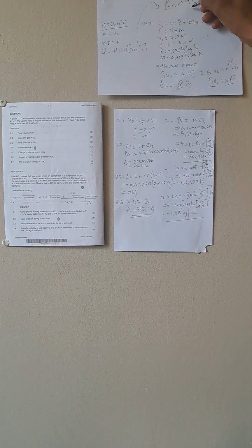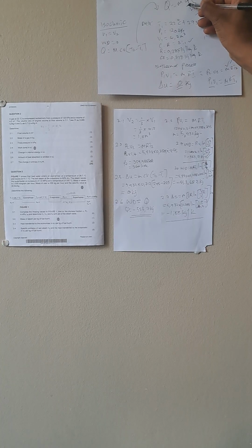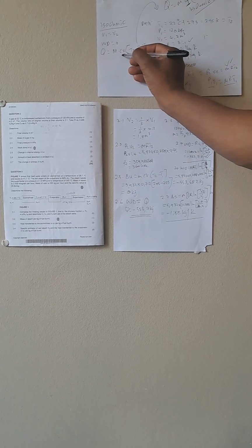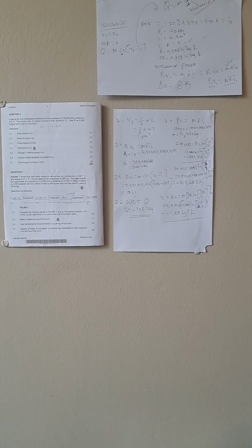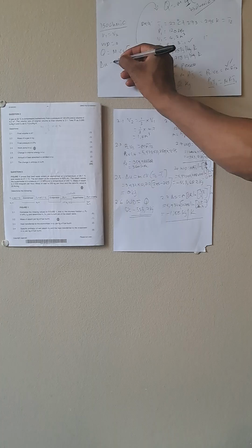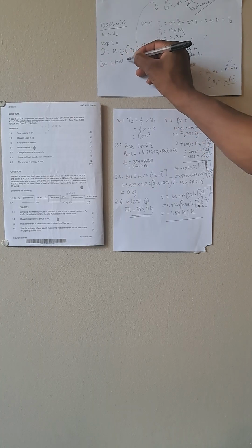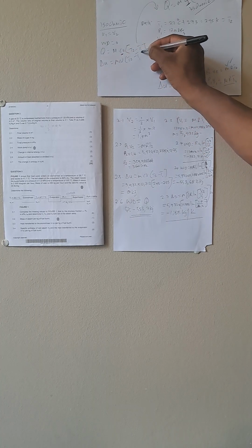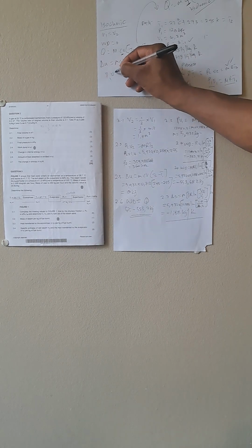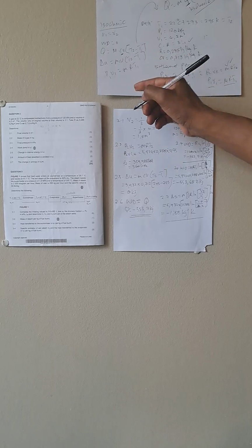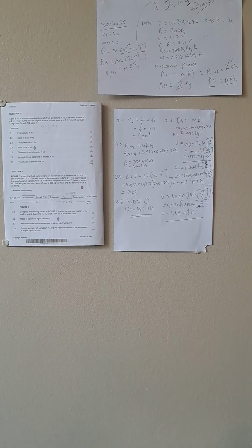So in an isobaric process we use CP, constant pressure, but in constant volume we use our CV, which is also our specific heat capacity at constant volume. And lastly, our delta U, which is our change in internal energy, equals mCV into T2 minus T1. Now, the other formula, P1 V1 equals mRT1, we can use anyway, regardless of the